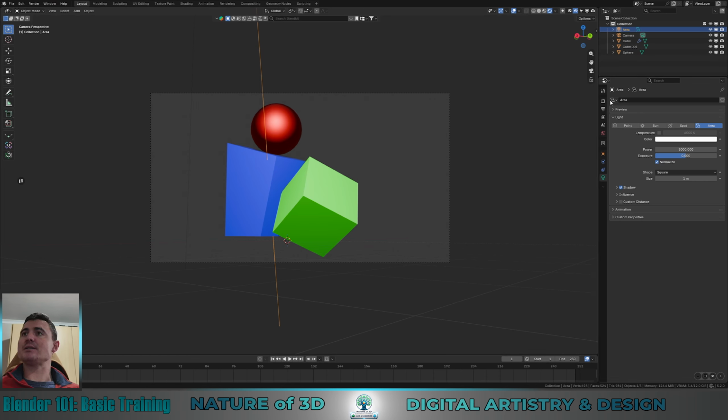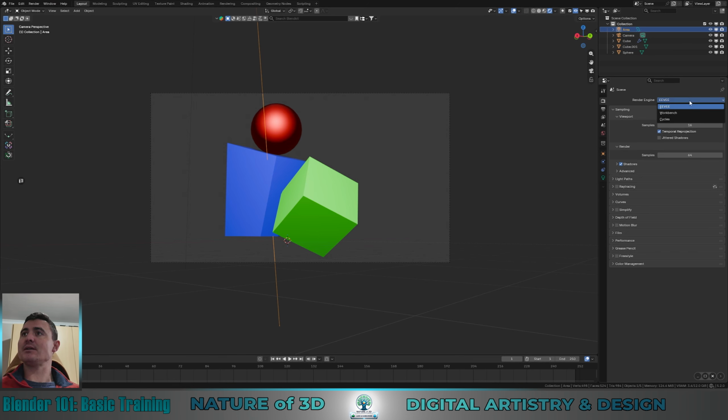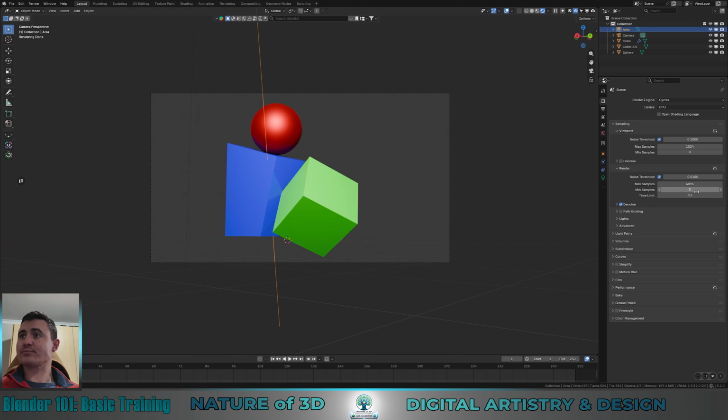So what you can do next is go to the render button and click on Cycles. You can lower the samples a little bit to, let's say, 1000. We can turn on the denoise, that helps a lot. And when you're happy with your camera viewport and your light, because just remember, this is just a basic setup.